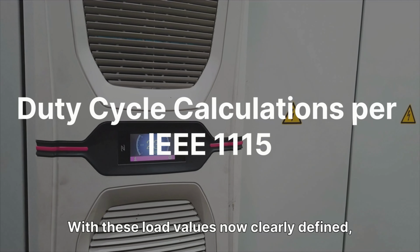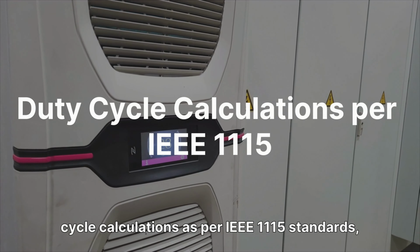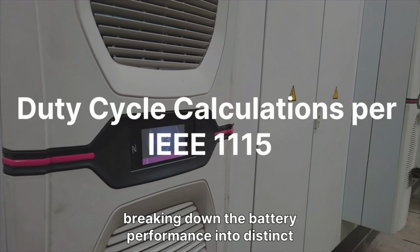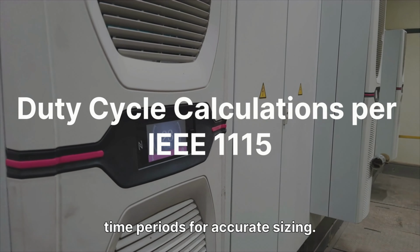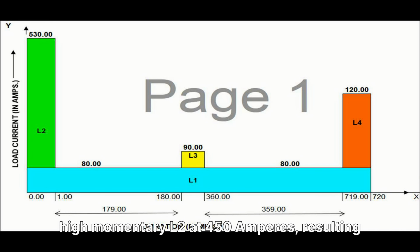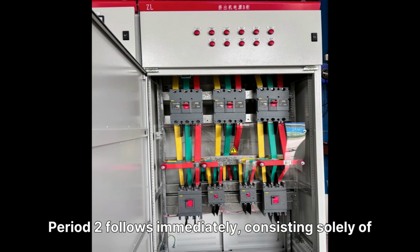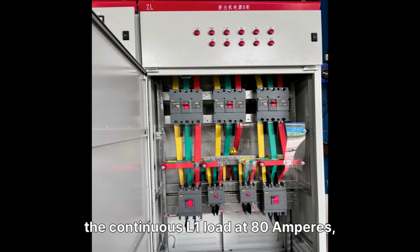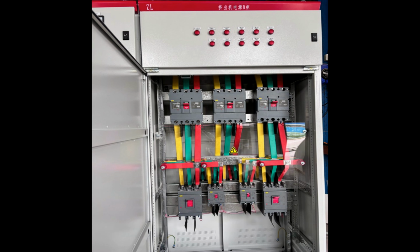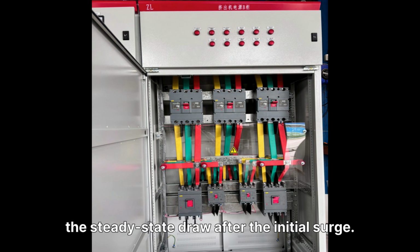With these load values now clearly defined, we apply them directly to our duty cycle calculations as per IEEE 1115 standards, breaking down the battery performance into distinct time periods for accurate sizing. Period 1, from the start, combines the continuous L1 at 80 amperes with the high momentary L2 at 450 amperes, resulting in a total demand of 530 amperes for the initial 1-minute duration. Period 2 follows immediately, consisting solely of the continuous L1 load at 80 amperes, extending until the emergency phase begins, representing the steady-state draw after the initial surge.